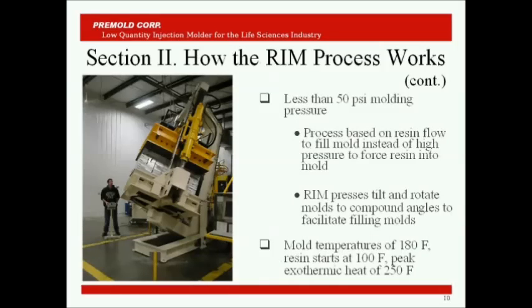Now, air vents are placed at the top end of the mold here as it's oriented at its compound angle. And as resin fills the mold from the bottom, the air escapes out the top end of the mold through those vents. The computer controls on the dispensing unit that we looked at previously stop the injection of the resin when the mold is full.